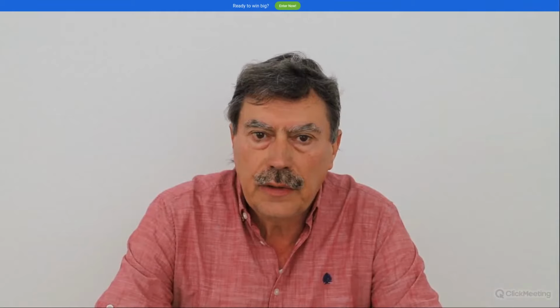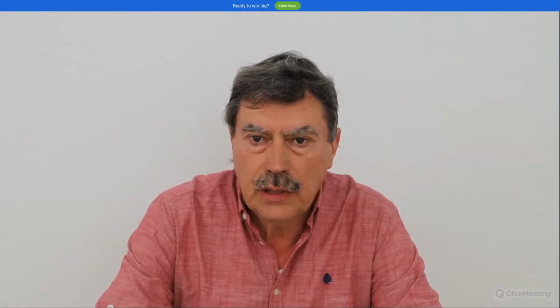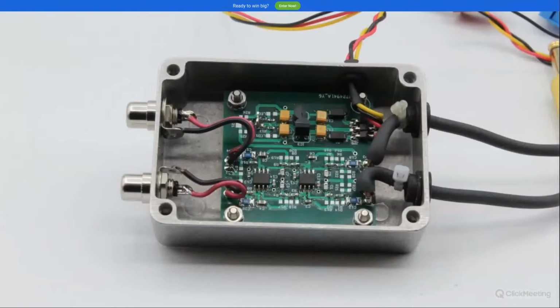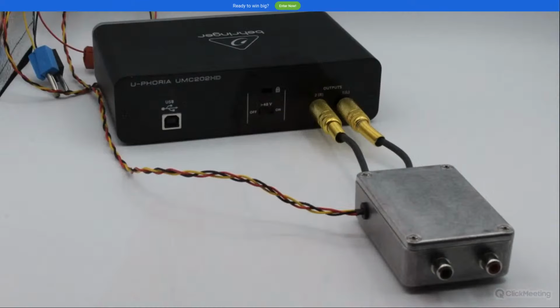If you have another interface or do not like to open it, there is an external filter which fits into an aluminium housing from Hammond. It is powered with ±15 volt and has its own ±12 volt regulators on board. The filter can have gain to get higher output amplitudes. It might be connected at the outputs of the interface.